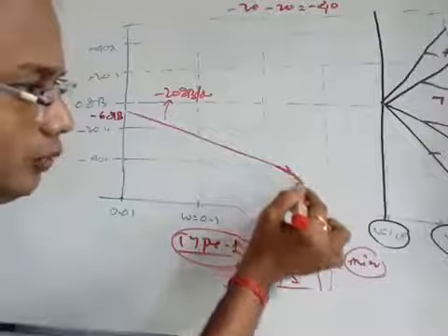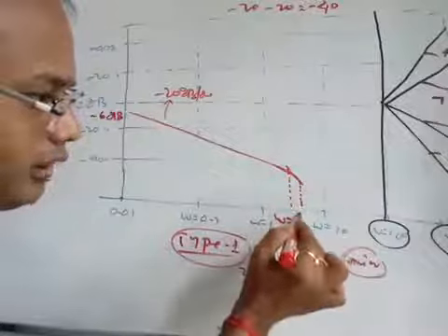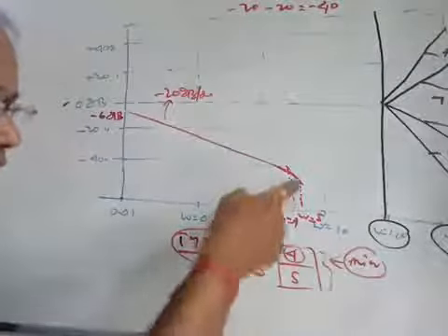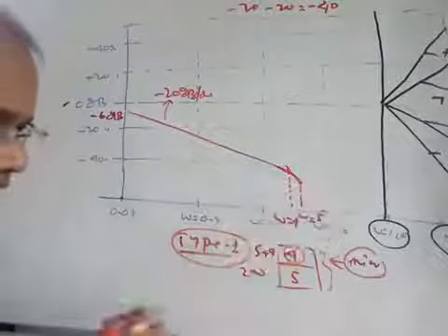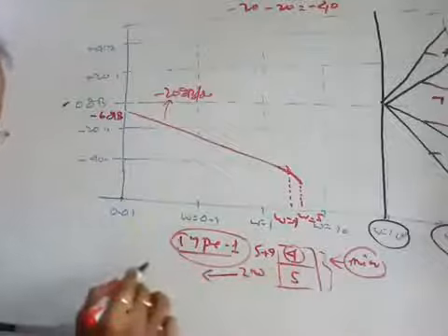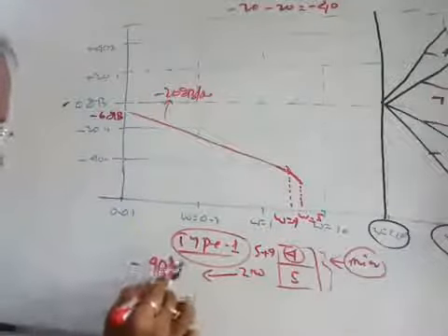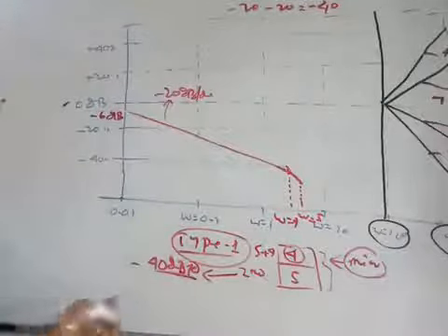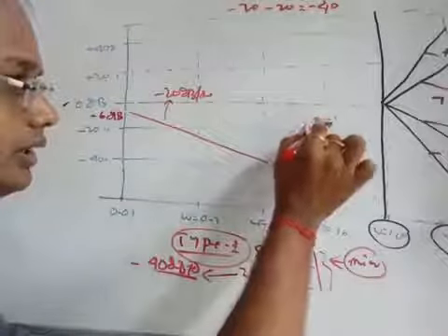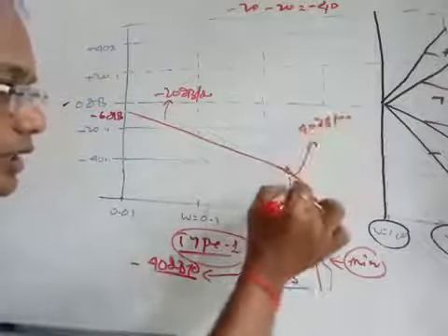This is the slope. So up to omega equal to 5, this goes up to omega equal to 5. And when it reaches omega equal to 5, what does it say? This is a second order factor. That means at omega equal to 5, the slope contribution is minus 40 dB per decade. So this is your minus 40 dB per decade. So up to this you have reached.